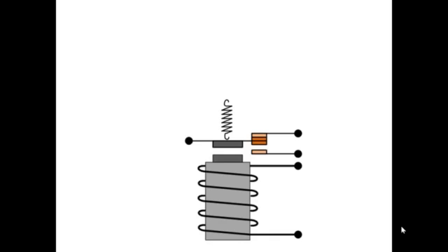And that could be one device or many devices in a separate circuit. And remember, the relay coil represents collectively the combined state of those devices. So you can use the normally closed contact to query the coil to see if it's de-energized, or you can use the normally open to see if the coil is energized.